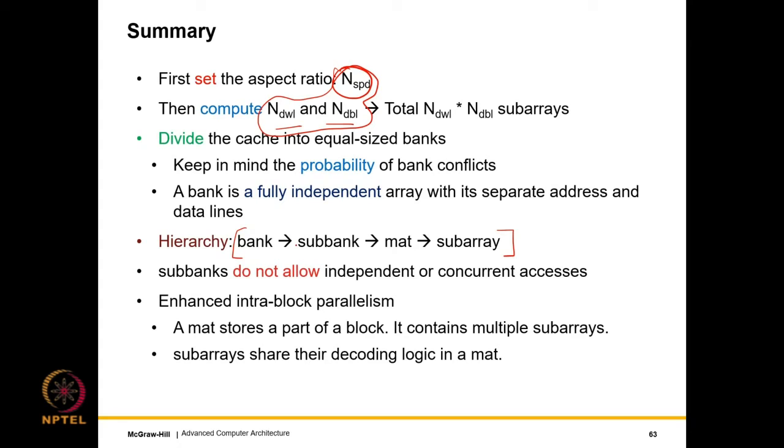So given this, we need to now go one more level down and figure out that, let's say, given a subarray, how do we find its timing and power? So finding the power is simpler given a proper model of the circuit, but the timing is much harder. So we will discuss the Elmore delay model that will teach us how to compute the timing of such complicated circuits.